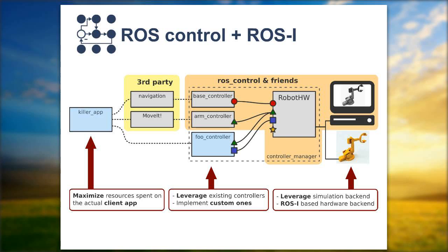In this case, for ROS Industrial, you would use the ROS-I client for this, but you could leverage the Gazebo bindings out of the box, which, as far as I'm concerned, ROS Industrial right now doesn't have as a generic integration with Gazebo. And this is, I think, very important, not only because of the physics, but because it also allows you to integrate perception in your simulation.